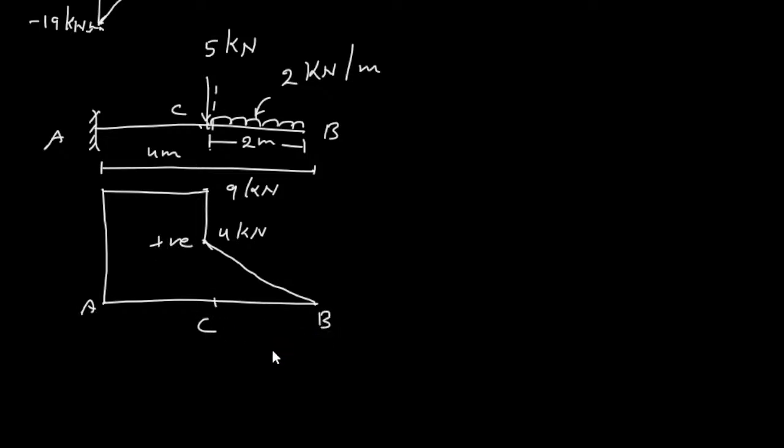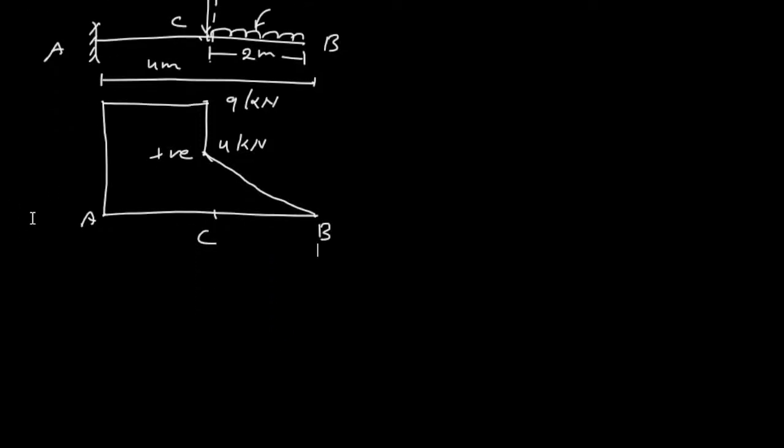If you want to draw your shear force diagram from end A, then you first have to calculate the reaction at point A, and the calculation of the reaction is the same as we did in the last problem, that summation of Fy is 0.